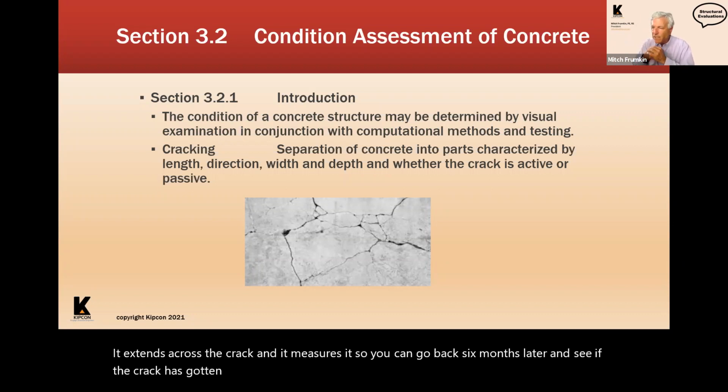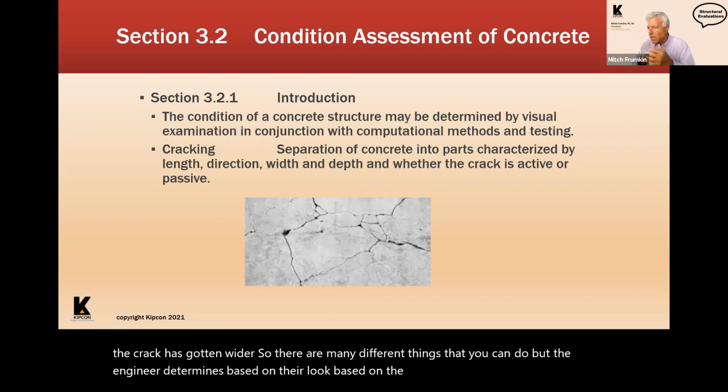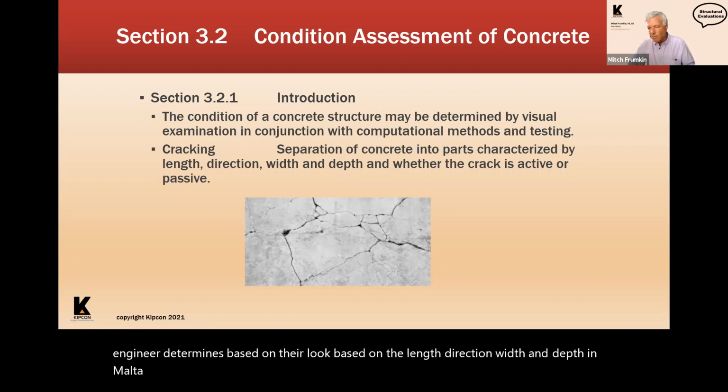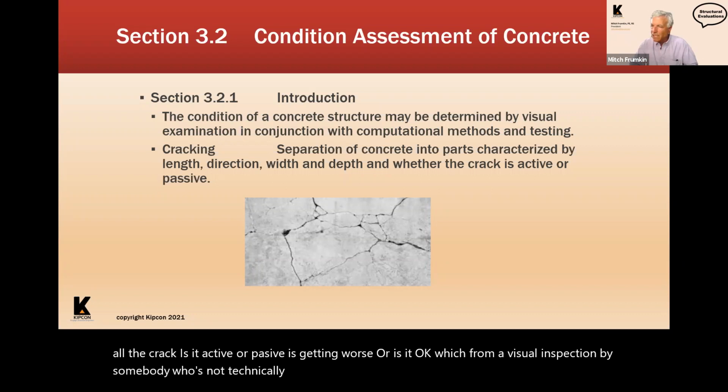So there are many different things that you can do, but the engineer determines, based on their look, based on the length, direction, width, and depth of the crack, is it active or passive? Is it getting worse or is it okay? Which from a visual inspection by somebody who's not technically knowledgeable in structures will not give you the answers you're looking for.